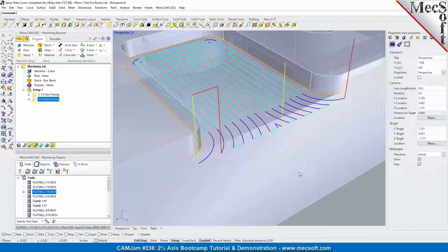And it's saying that line segment is really where the stock material starts. So that's how it figures out how to enter the material. That's why you're seeing the entry exits go through that line segment. So you can use an open curve in facing, but internally we will add a line segment to close it up. So it's important to know that.